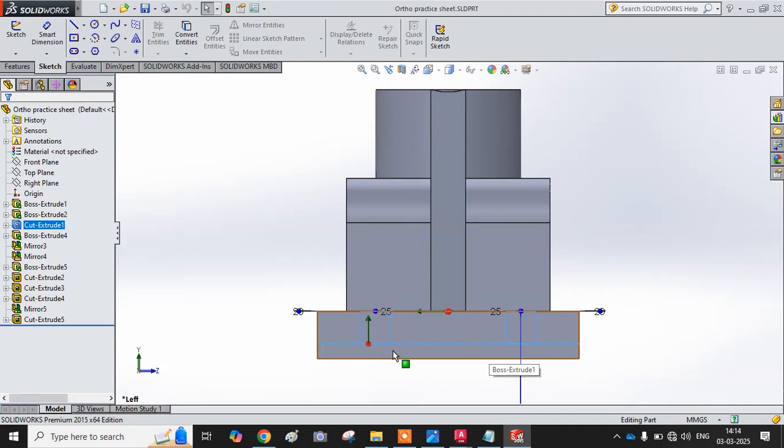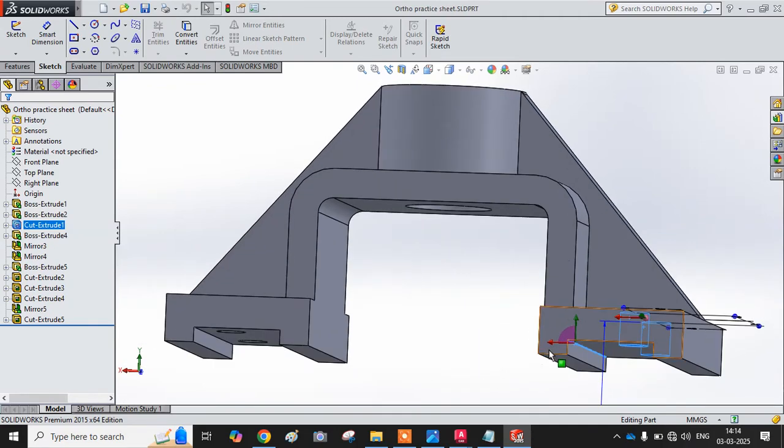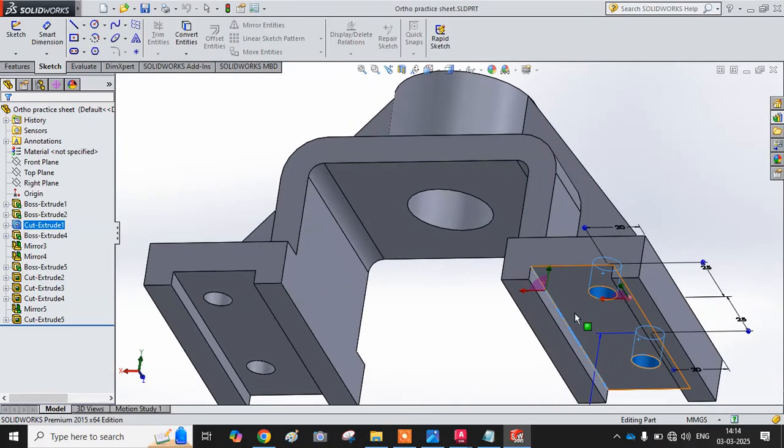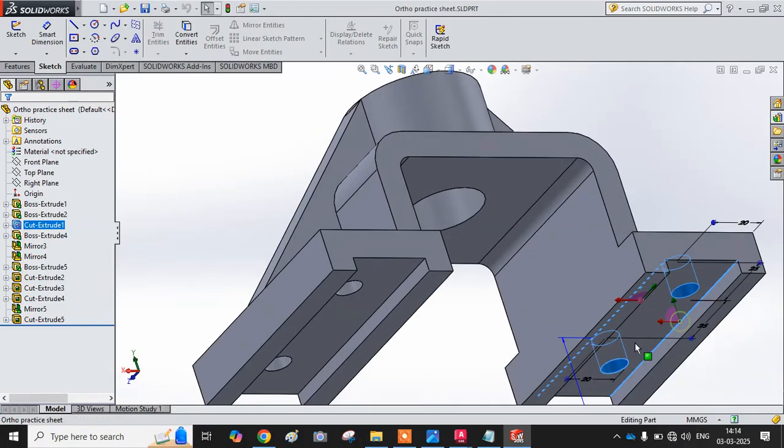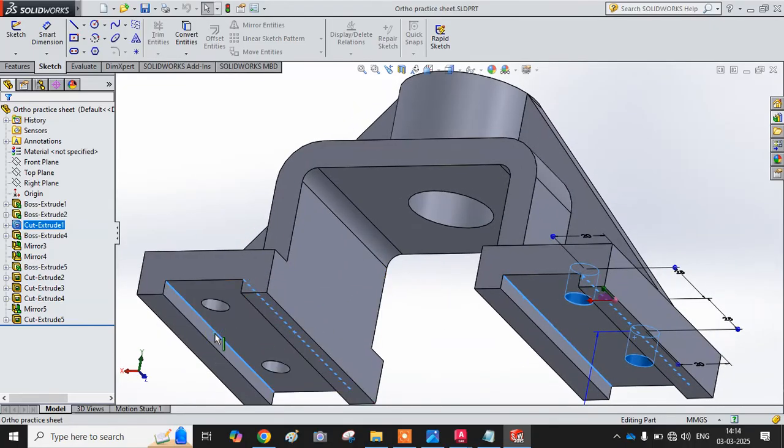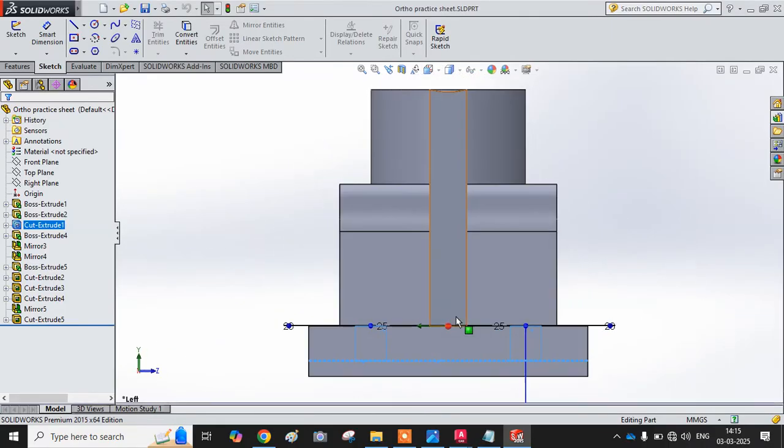So if I show you the left hand side view, ये देखो ऐसा आएगा. Can you tell me what is this hidden line? ये नीचे का edge है ये देखो यहाँ पे. You can see this edge, then this edge, दूसरा edge ये है, तीसरा edge ये है, चौथा ये edge है. ये चारों का मिला के सिर्फ एक हिडन लाइन आएगा, which will be this one. Is it clear?